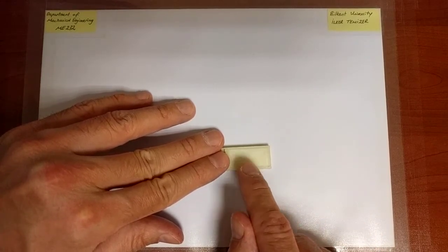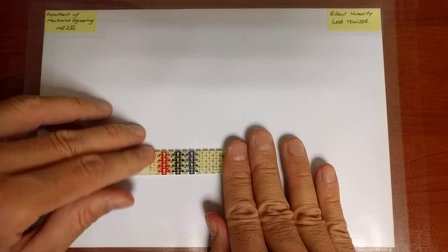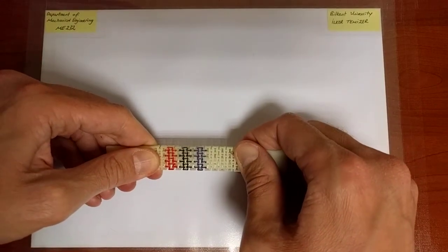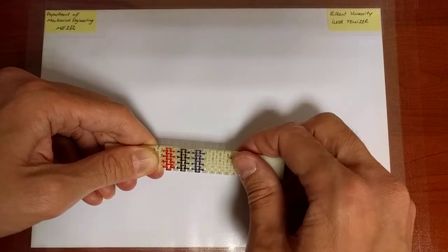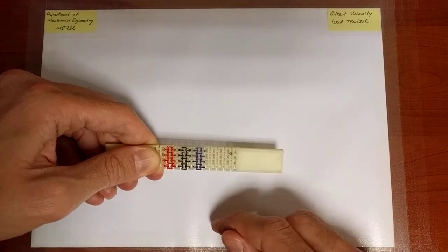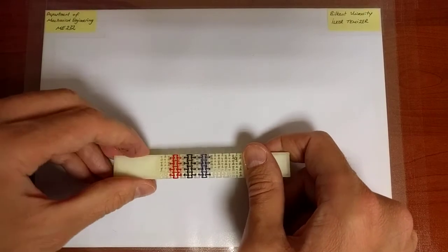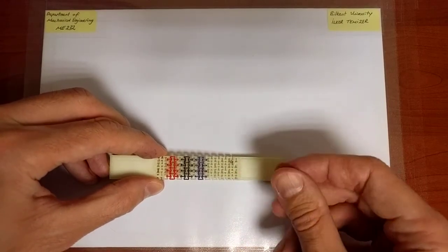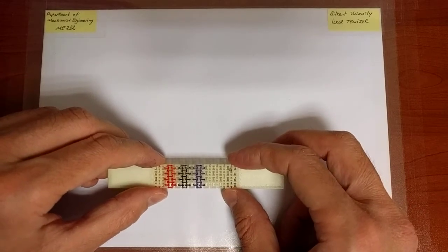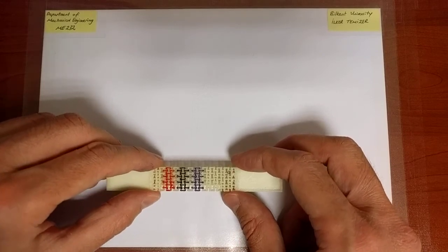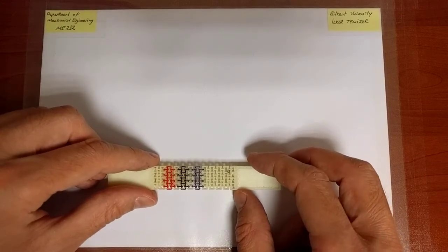I assume that the infill ratio, if it were 100%, then it would be 0.5. But here, there are pores, and that induces the Poisson ratio to be drastically different, in fact, even negative. So here is 0.5, close to being incompressible, and here it's negative, a huge difference that arises from the microstructure of the material, or the 3D printed structure of the material. So that's the way the microstructure, the internal ingredients, and the way they are arranged influences the mechanical behavior of the structure. And anisotropy, general anisotropic behavior, is how we characterize that mechanical behavior.